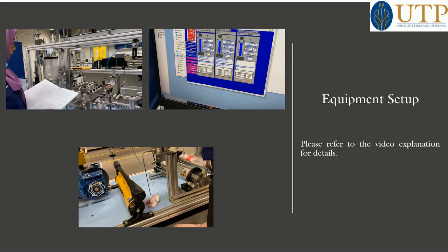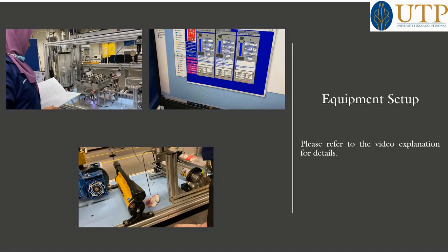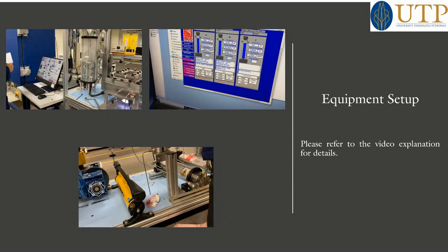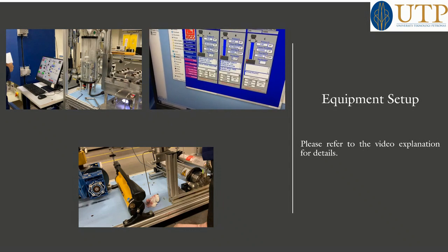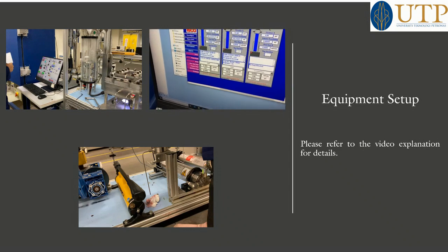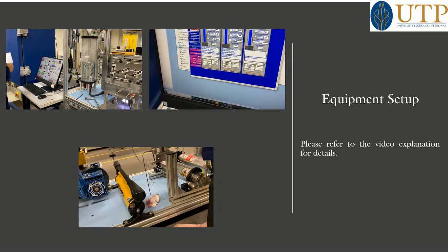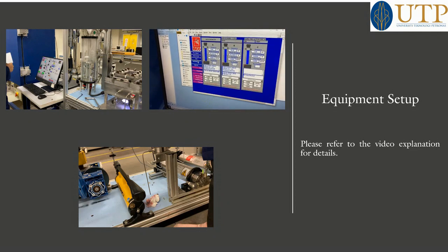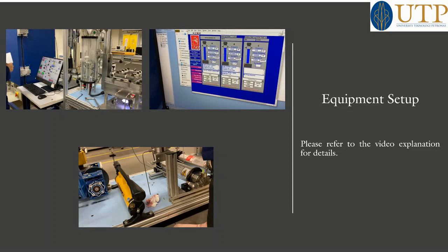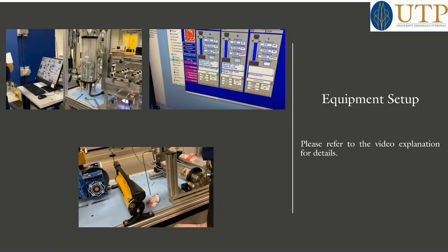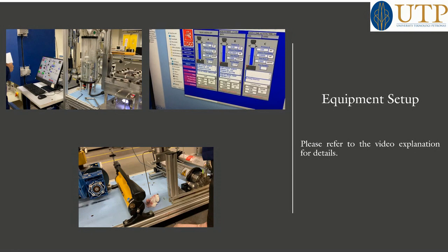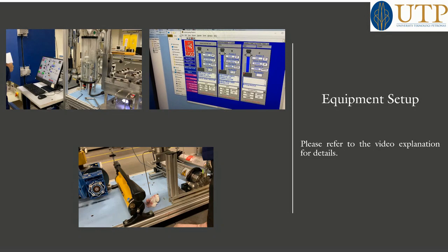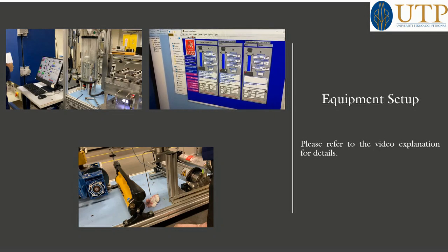Now the brine injection part. So we can see that the volume is 103 and this is also 103. So now I will stop running. So I stopped running for both. Now make it continuous constant flow, make it remote. When we make it remote, that time it will work for this. When pump A works, pump B will be standby. When pump B works, pump A will be standby.